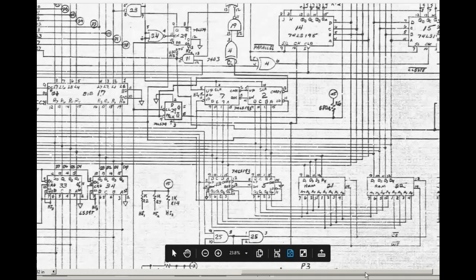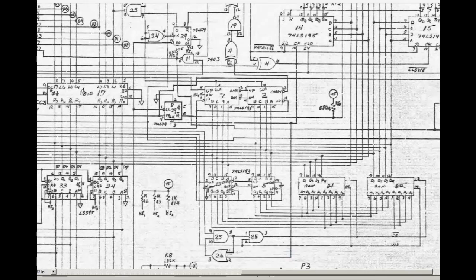So for example, we've got the nano processor at the top just off the screen. The data from it comes out of its data bus through this buffer onto the main data bus on the board. And if we want to store data in the RAM through these two devices over here, the data is of course inverted, but we can't just make the assumption that when we read it back it's inverted again, so we end up with what we started with.